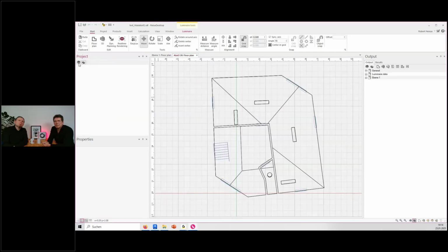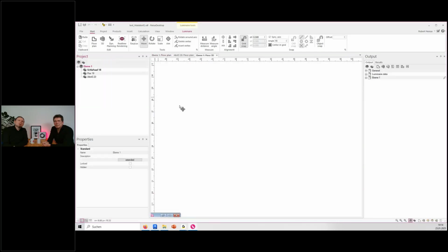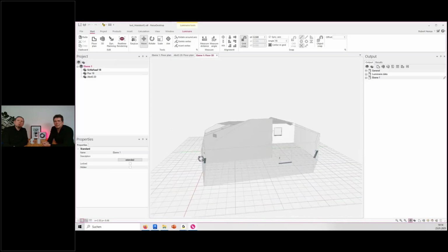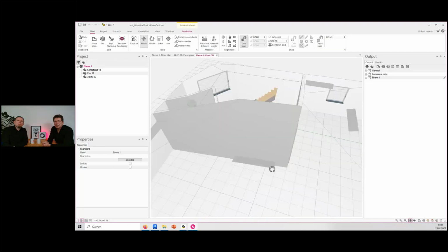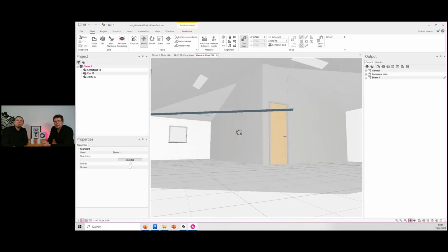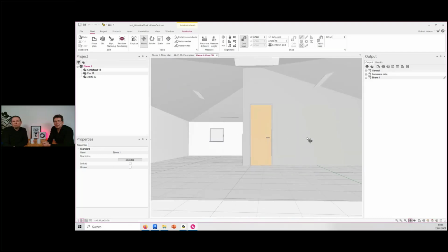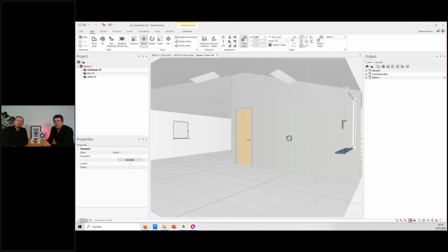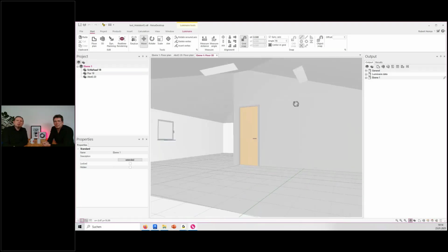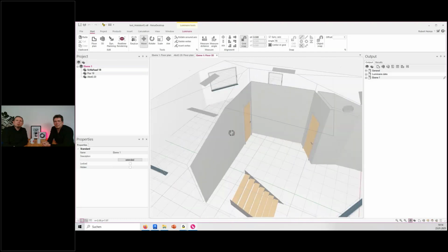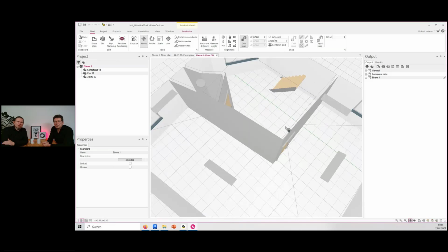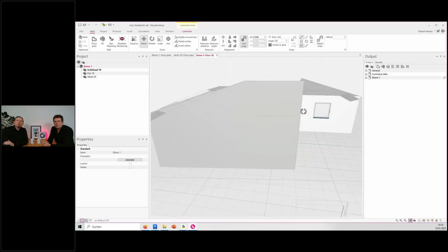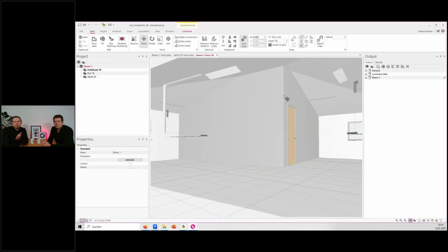Oh, it was the wrong button. This one, and you can see now we have this roof structure, which is not easy or not possible to extrude, covered from Revit into ReluxDesktop. And now we can do lighting design here, or exchange the luminaires and go on with it. So we can use Revit as a kind of rooftop editor for ReluxDesktop.